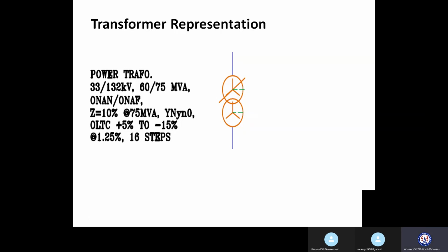Okay. Now serial number 1: transformer rating up to 2.5 MVA, percentage impedance value 4.25. So for a transformer rating up to 2.5 MVA, the percentage impedance value is 4.25. Then next, transformer rating 5 MVA, percentage impedance value is 5%.